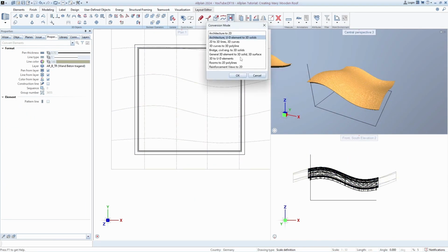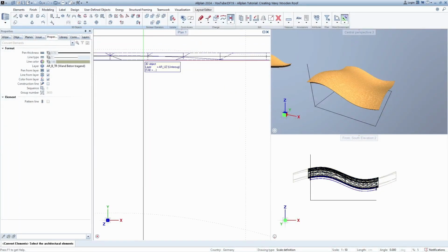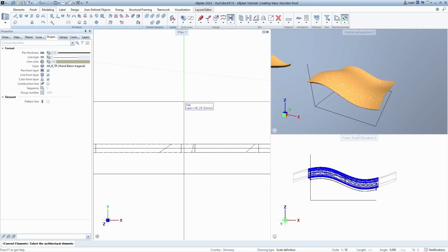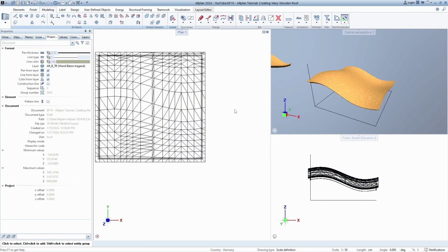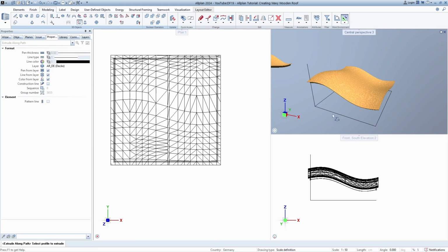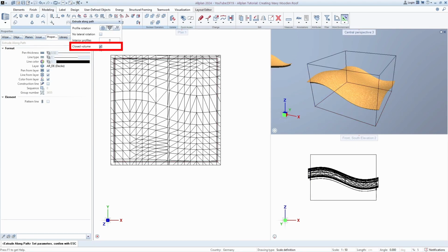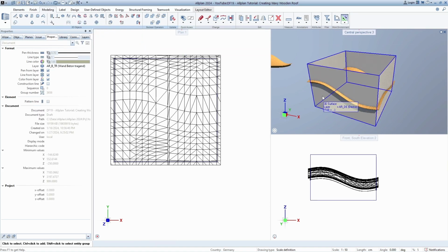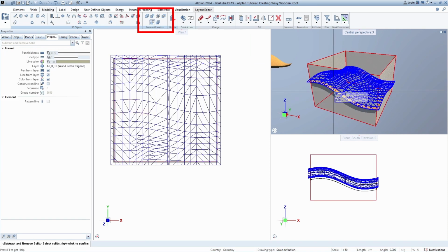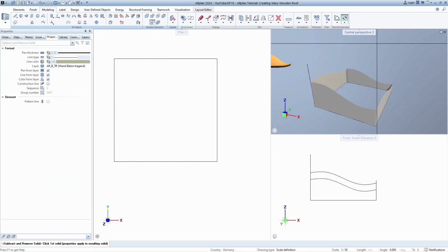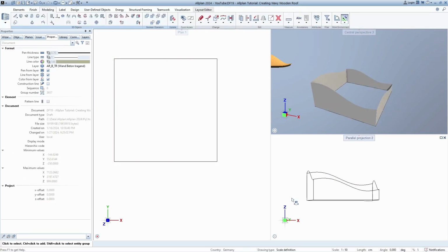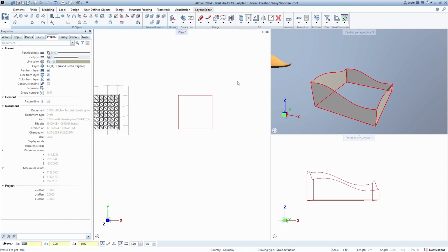Using the Convert Element tool, convert our beams and slabs into 3D bodies, so that we no longer need a plane and can freely select and delete it. Now, using the Extrude along the path tool, select the square and line, turn off the option for closed volume, escape to finish the command, and now, given that we only have 3D bodies left, we can use Boolean tools to cut our facade. First, we will cut the facade with the roof and then with the beams. Delete unnecessary lines and move the facade to initial distance.